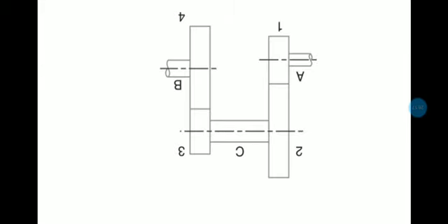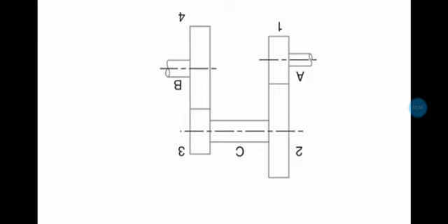Then the last question, reverted gear train. The figure is shown here. This is the figure. On reverted gear train shown in figure 3, two shafts A and B are in same straight line, geared together. Then gears connect shafts A and C. Module is given; in both cases module is given. Speed of shaft A is greater than 12 times speed of shaft B, and ratio at each reduction is same.